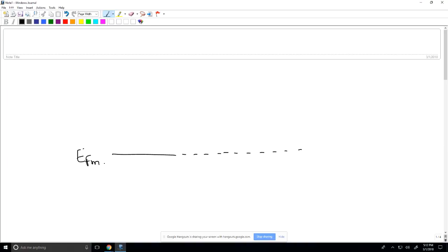A metal has a much higher charge density than a p-type semiconductor. So holes from the semiconductor move towards the metal and basically create a depletion region. The vertical dotted line I'm drawing here represents the depletion region. Because holes are lost on the p side, we say that